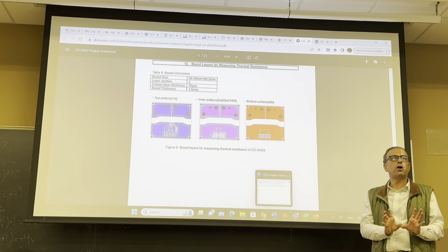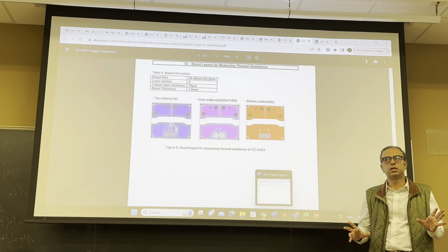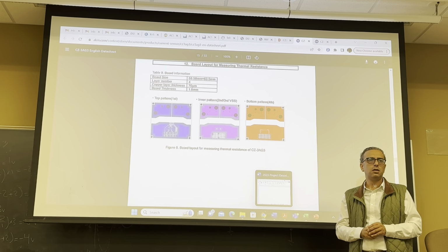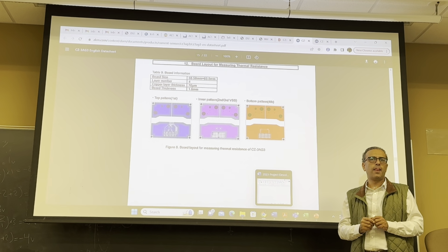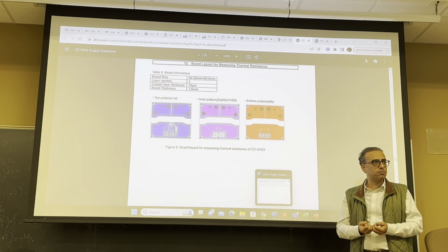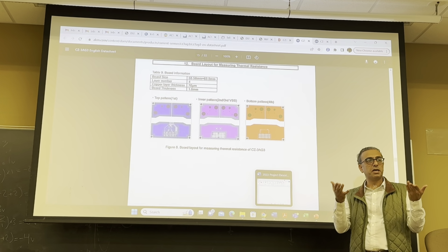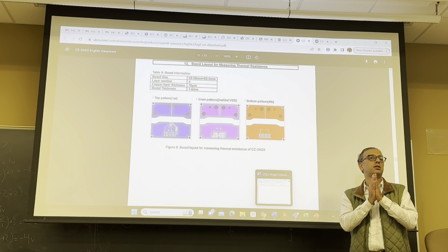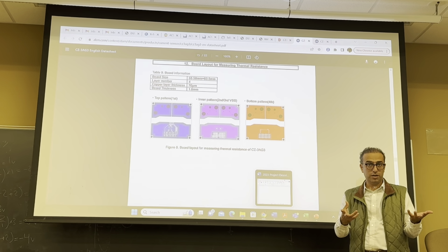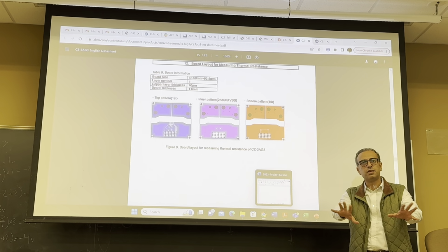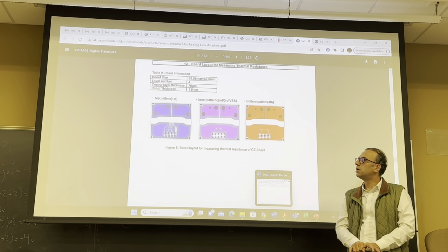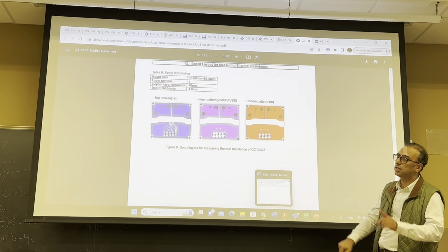But what you can see is there are always empty spaces, right? You should provide clearance, not because of the voltage, but because of magnetic field manipulation. These are magnetic fields, and you use a magnetic detector, which has higher sensitivity than other components, so they don't want anything around it. So that's number one.